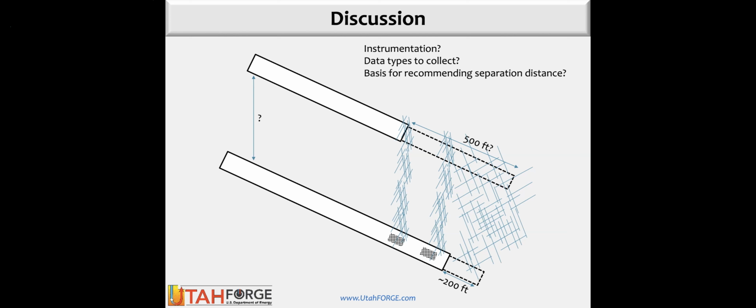The base plan, without any further information, is that we will offset directly above. We had pretty much strongly upward fracture growth, upward stimulation, upward microseismic from 16A. Your point about a connection versus the best connection is exactly what I'm trying to get to. If we want to just guarantee a connection, we could put these wells 25 meters apart and be pretty certain we're going to hit them. But there are other things we need to do with these wells.